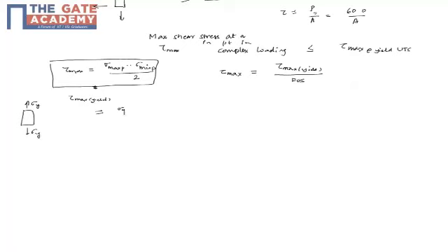So that becomes the maximum principal stress, and the minimum is 0, divided by 2. So this is my yield maximum shear stress. We know the yield stress is given, which is 310 MPa. So 310 by 2 is 155.